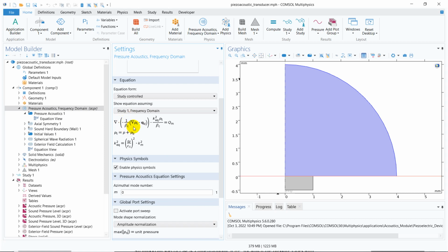You can quickly have a look. There is a Laplacian, so in the Laplacian 1 by meter square will come. There is a density rho, that will be kg per meter cube, and you have a pressure. That pressure has a unit of Newton per meter square, and if you calculate it, you will get 1 by second square.